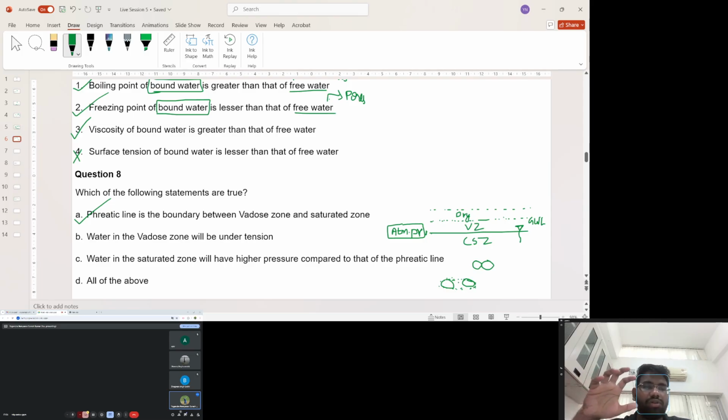That is what usually occurs. But in a partially saturated system, soil will be in compression and water will be in tension. Since water is in tension, it tends to pull the soil grains together. Hence, soil grains will be under compression and water will be in tension.